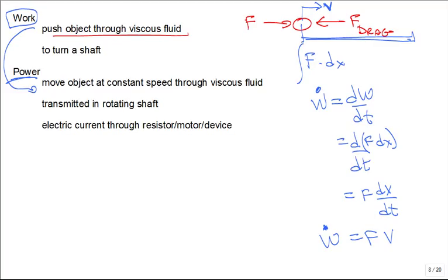Okay, we'll get to where the aerodynamic drag, this is in the car application. The aerodynamic drag is often proportional to the speed squared by itself. And when you have the aerodynamic drag proportional to the speed squared, and then you multiply by speed again, you find that the power goes up as the speed cubed. Right?